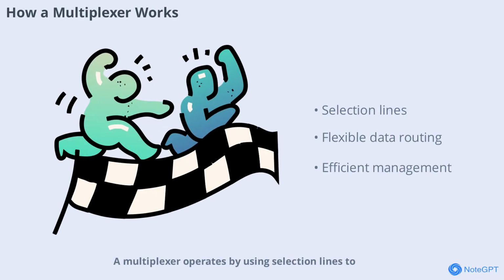A multiplexer operates by using selection lines to choose which input is connected to the output. For example, a 4-to-1 MUX has 4 data inputs, 2 selection inputs, and 1 output. Depending on the selection input values, the MUX forwards the corresponding data input to the output. This flexibility makes multiplexers essential for efficient data management.